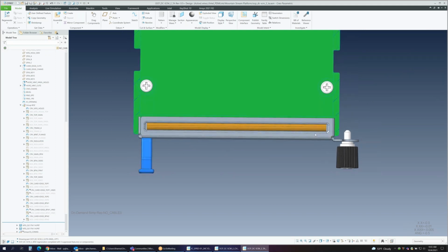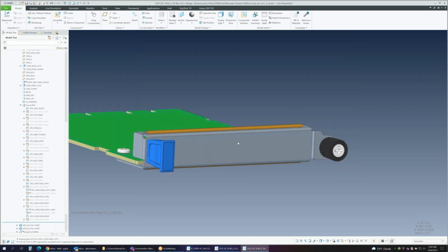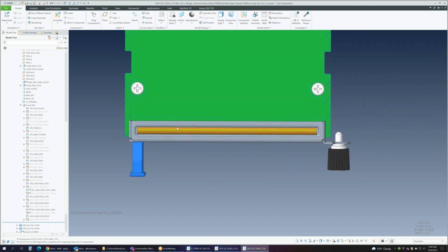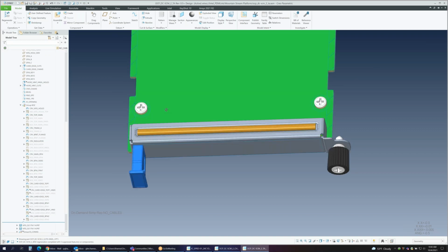It's essentially the same if you look at the edges of where the mounting holes are in relation to the edges of the flanges, and the depth of the flanges, all of those things. One thing to note is that the depth of the overall bracket, at least on the top and sides, has shortened from where it was on the OCP NIC. That's again to provide as much topside height allowance as possible for components to go as high as they can in this area. So that's why it's been shortened.